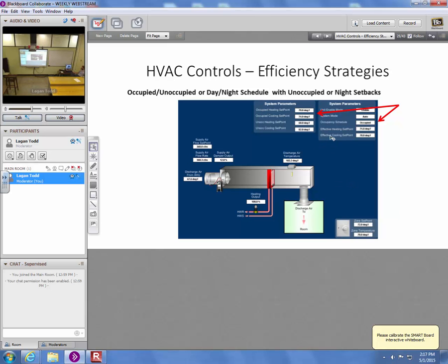And so you can see on this screen, it tells us, here's supply airflow set point. So that's a set point that's being calculated by the controller, coming out of the logic. There's supply air flow rate, which is being measured by the flow station that's installed here. There's supply air damper output, so that's the command to this damper, which it shows at 12%, so that would be like 1.2 volts probably, if that's a 0 to 10 volt actuator.